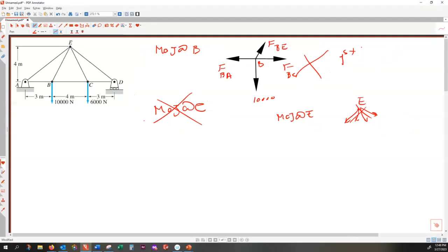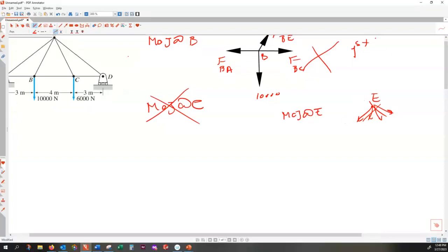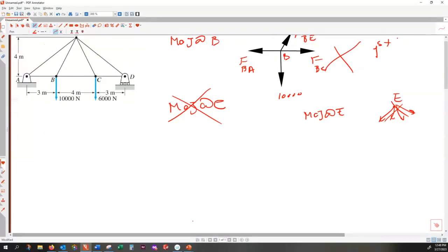So if I release this, I make the free body diagram overlaid on the same diagram. So here, I don't know the direction of the forces. So let me assume that these are positive. And the next step is to label them. That one is labeled AY, AX, and this one is DY. All right. So that problem, is this solvable? It has three unknowns and three conditions, right?